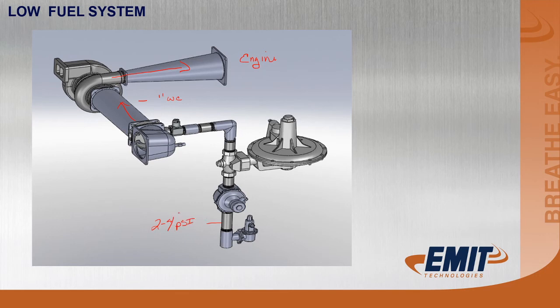The problem with that is you would never be able to overcome the boost pressure on a high pressure fuel system. So they developed a low pressure fuel system. And in our industry, they use this for low suction pressure units, or units that have very low wellhead pressure, so they can get them started. The advantage to this is you don't need very much fuel pressure at all.